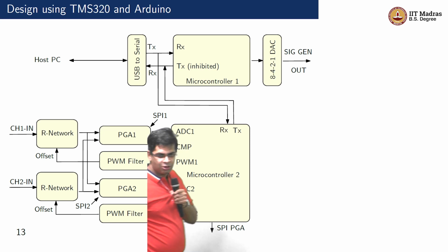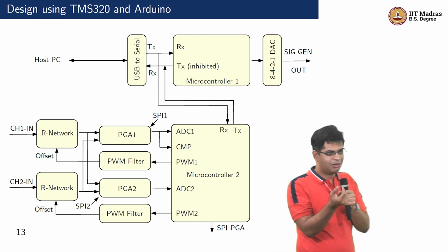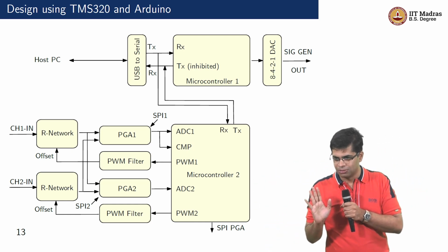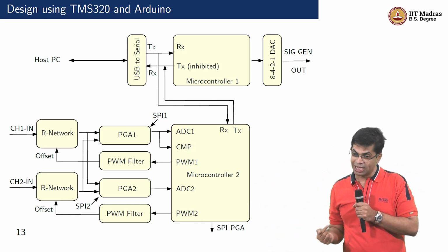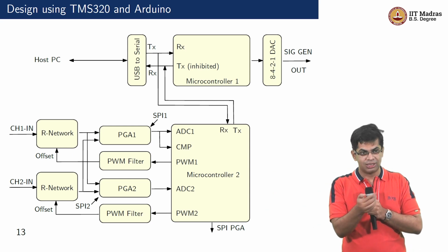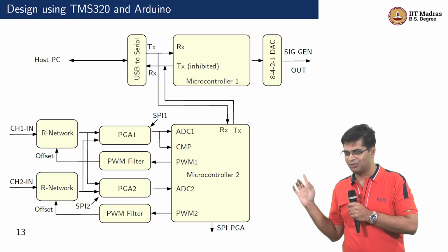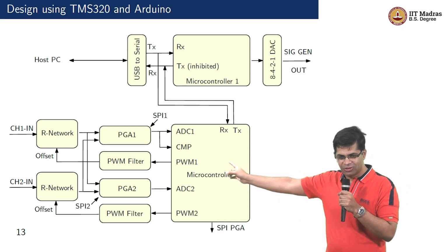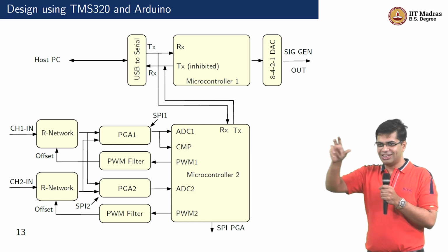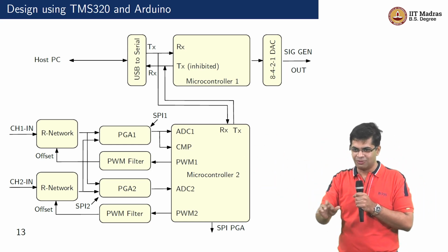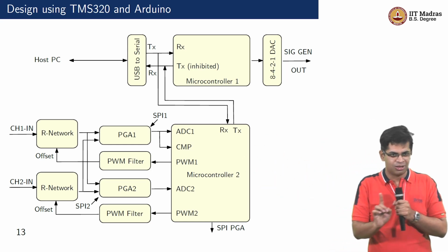Depending on what is the tag, the appropriate fellow does the job. The oscilloscope has to send data back. Signal generator does not have to send any data back. So that was the trick that we had to use. The way we have configured, using just the Arduino board and the TI chip without having any additional USB.